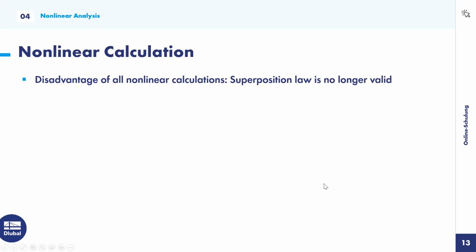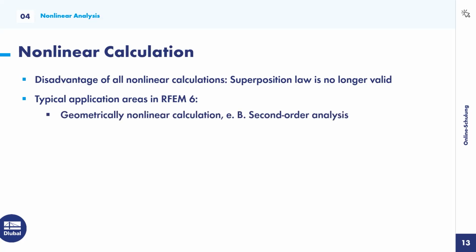The problem is now with nonlinear systems, this is not possible anymore, because the loading from the first load case can influence the system in a way that it changes its behavior for the other loading. And that's something that can happen with different applications. One would be the geometric nonlinearity.